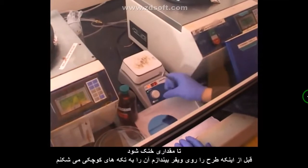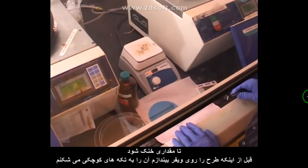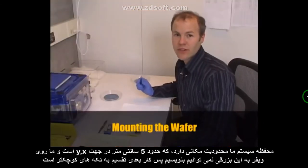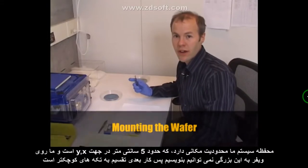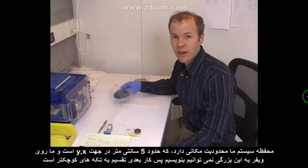Let it cool. And then before we pattern the surface, we'll break this into smaller pieces. The chamber size on our system is limited to about 5 centimeters in the X and the Y direction. So we can't write on this entire wafer.